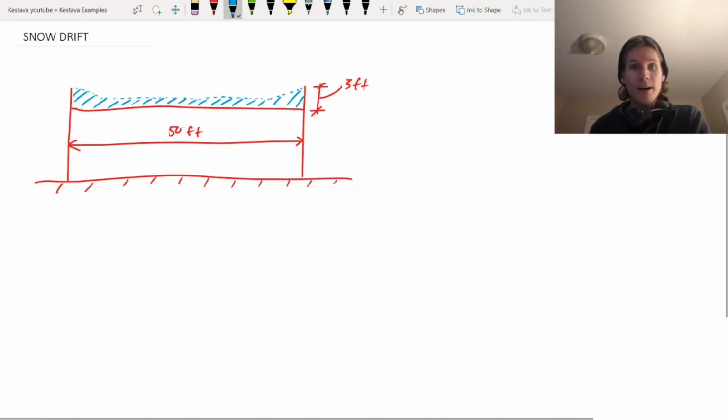They are those objects that create those little crevices and corners and nooks where snow can accumulate, and over time you could actually have drifts of snow or big piles of snow that weigh a lot more in critical locations, kind of like right here, where there's much more snow that's loading the structure than you would have in a typical part of the roof in the middle of it somewhere. So that's snow drifts, and we need to figure out, well, how heavy did those snow drifts get, and what do we need to design for in order to accommodate those snow drifts?